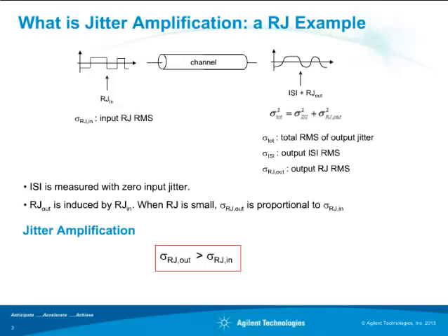Okay. Yeah, I think in that context, phase distortion actually means the phase velocity dispersion in a lossy channel, meaning different frequencies have different phase velocity because of channel loss or channel dispersion.